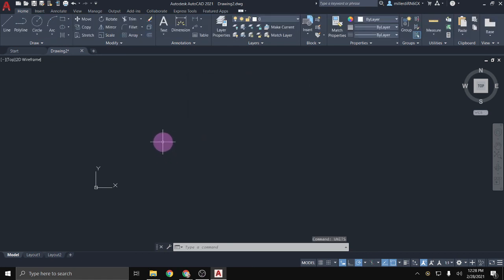Now when I go into the line tool, so L, enter, and I click somewhere to start my drawing, we can see that in that text box, instead of it just being like the number 400 like it was before, it is now reading feet and inches out. When you are typing your measurements in AutoCAD, it is going to infer that you mean inches unless you tell it otherwise.